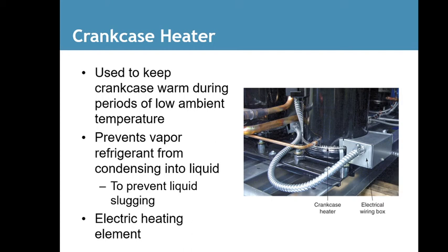And I mentioned a little bit more about this because you're not going to see them a lot, but when you see them, sometimes they are problematic. Again, the wires on them, if your system's shorting out and you can't figure where the short is in the system, always check that, because again, this is not a copper device. This is a metal device, and constant rain outside will cause these to rust. Their wires will come off. So it's something you have to look at.